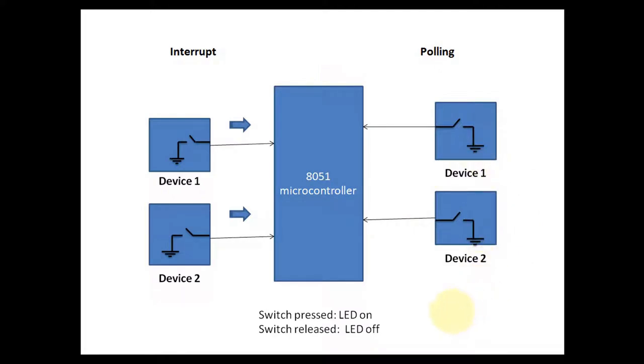In case of the polling method, when you write the code, you have to monitor the status of these two pins continuously. These two conditions you will write under a while(1) loop, where you are continuously checking the status of these two pins, and when the pin status goes from high to low, that means the event has occurred.